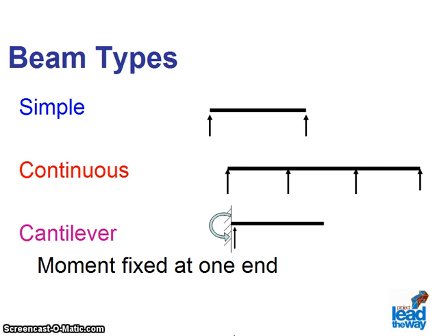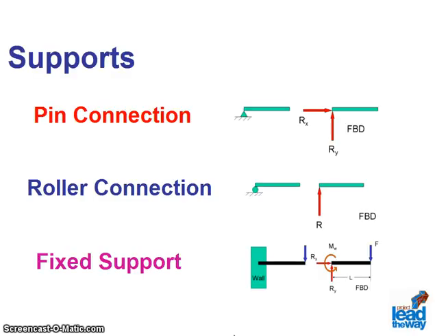The method of support is an important one. A conservative approach for calculating loads is to assume that the beam or girder is a simple span. Supports are determined by their method of attachment at the ends or bearing locations of the beam. These can be pin, roller, or fixed types of supports.